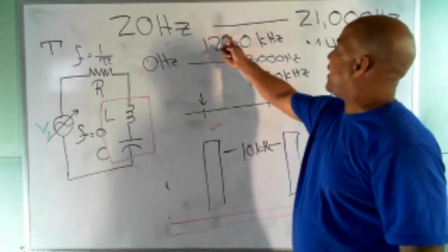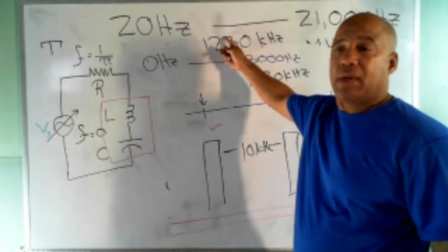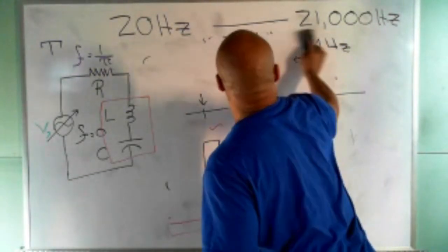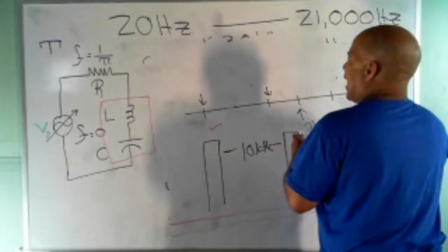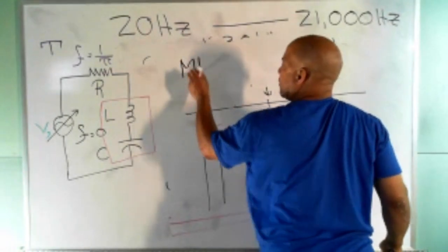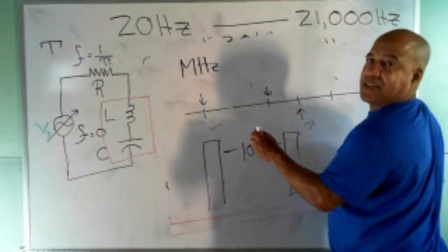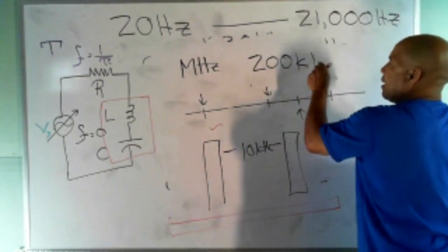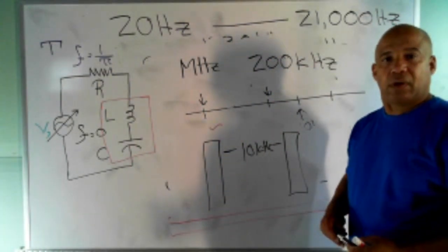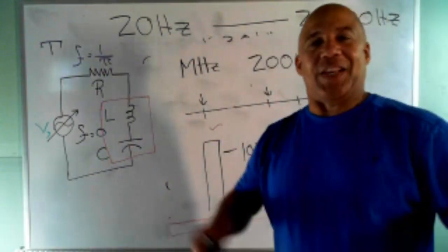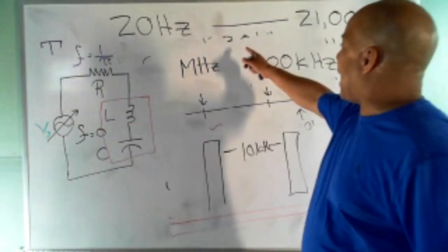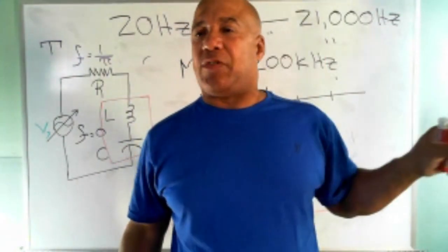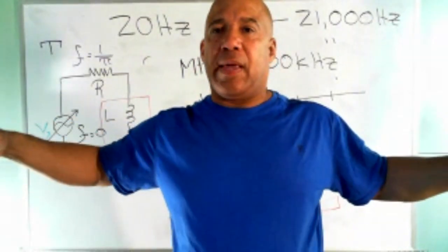I need 21,000. Well, if you look at your FM stations, which you've probably never done, but hopefully after this lecture you will, what you know is about FM. FM uses megahertz. And the FCC set the bandwidth to be 200 kilohertz. The bandwidth of FM is 200 kilohertz. It's huge. It's no problem to get all the hearing, all the audio. Matter of fact, in FM, they can actually transmit hidden signals to make things happen in your room if they want. Because there's so much room there.